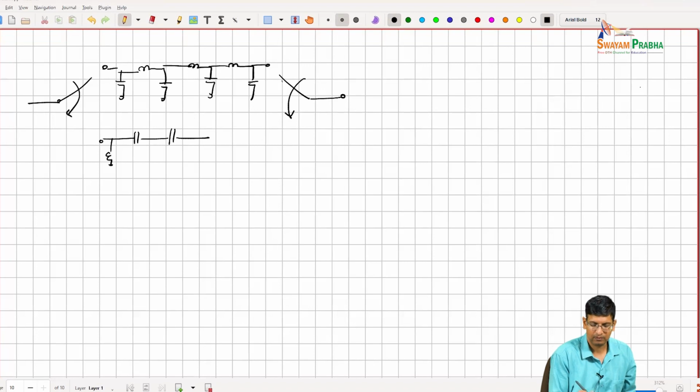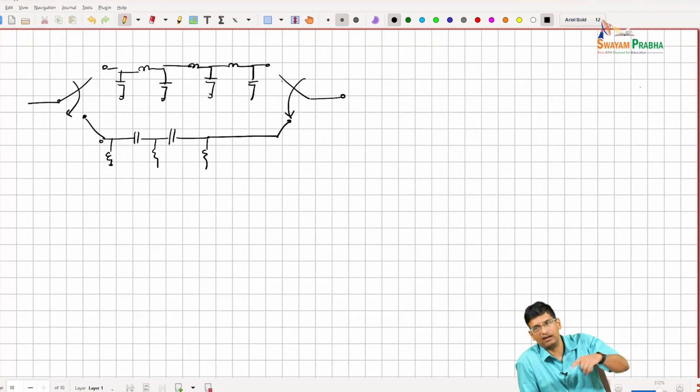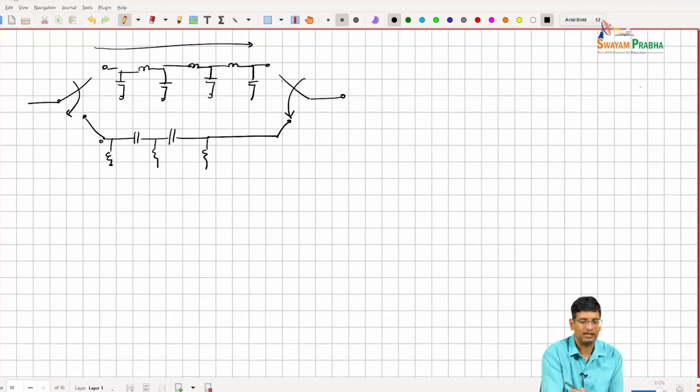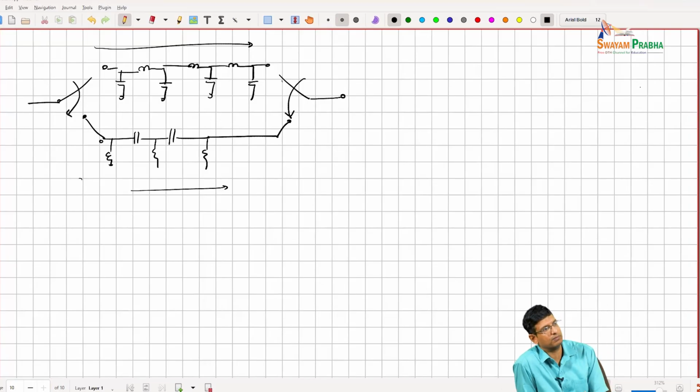right? And so one is giving you a phase lead, another is giving you a phase lag. So you are able to basically get some, because otherwise this path will be lossy, this path will not have any loss. So then you have that gain uniformity issue across phase shifter bits. Right. So you try to make both paths equally lossy, not just have one path that is clean.